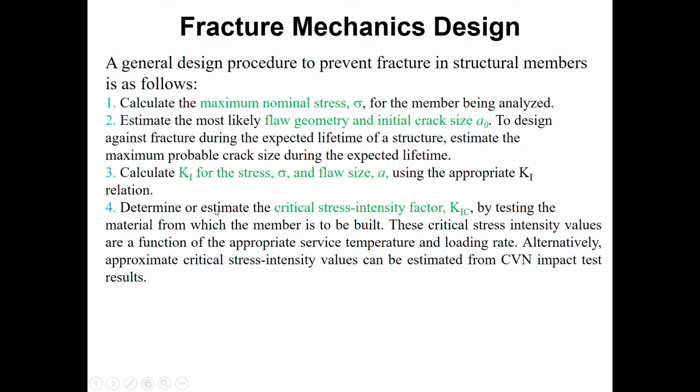Fourth, determine or estimate the critical stress intensity factor K1C by testing the material from which the member is to be built. These critical stress intensity values are a function of the appropriate service temperature and loading rate.